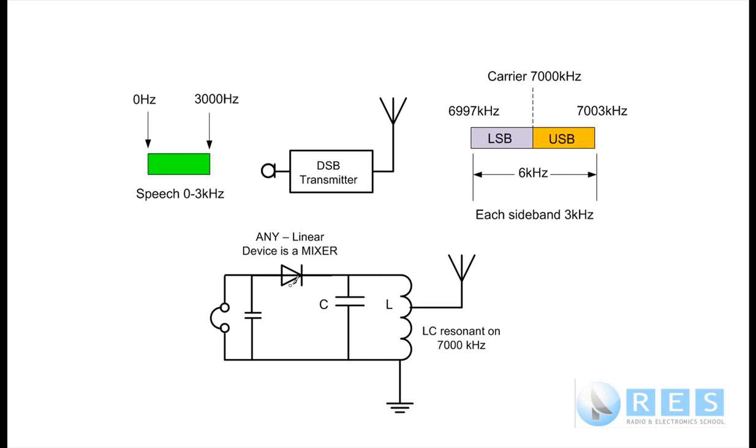A diode doesn't amplify, so we could have an amplifier here which is operating in non-linear mode. So we would get two things from the amplifier: non-linearity, which we need for mixing, and we would get amplification. But here we're just doing the simplest thing we can do and use the diode as a nonlinear device. So this signal is going to mix in that diode.